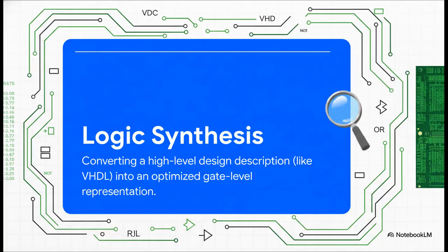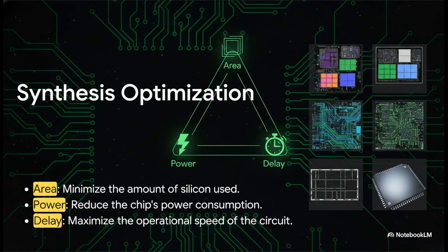And that's where this incredible process called logic synthesis comes into play. You know, the best way to think about it is like a special compiler, but for hardware. It takes our high-level, sort of abstract VHDL description, and it translates it all into a super detailed schematic of logic gates. What comes out the other end is something called a netlist. And that's just what it sounds like, a list of all the components and a map of how every single one is wired together.